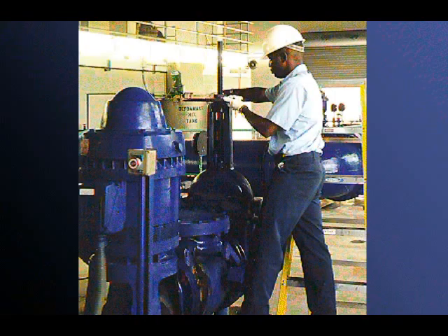While it is not a recommended practice, some operators actually control the flow by throttling the discharge valve. A better operating procedure is to only close the discharge valve to isolate the pump. If flow throttling is practiced, this will have a noticeable effect on pump motor amperage readings.